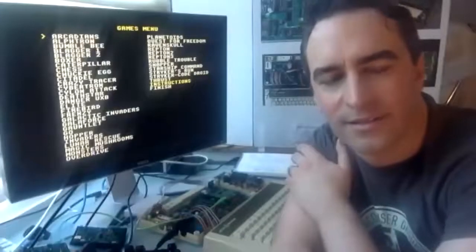And the PWM thing that I've used, I can't remember, I just picked it up somewhere on the internet and fiddled about with it myself. But I think it's like 5 or 10 lines of VHDL. It's not a lot of gates. It's a counter basically, a comparator, and then output. Toggle the pin when you go past the count.